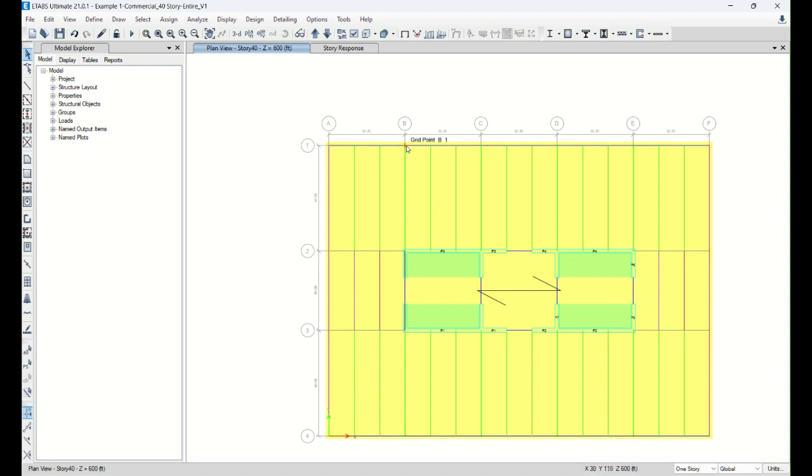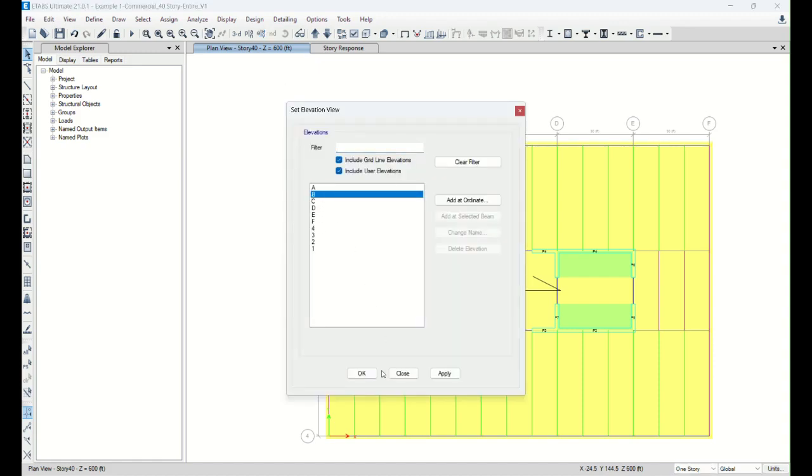Since we have a good series, a pair of walls right there, we may have a choice. Initially, we may provide some truss along grid lines B and E first. If two outriggers can handle the lateral stiffness, then that is okay. Otherwise, we may add another pair. So the outrigger trusses might be 2 or 4. I'm going to draw the truss on the B line and E line. So I'm going to go to elevation and pick up the B line first.